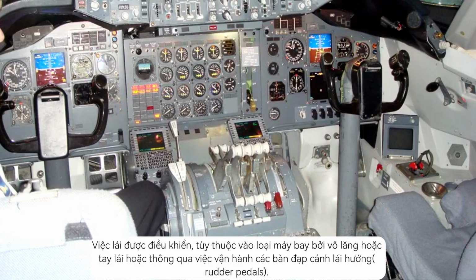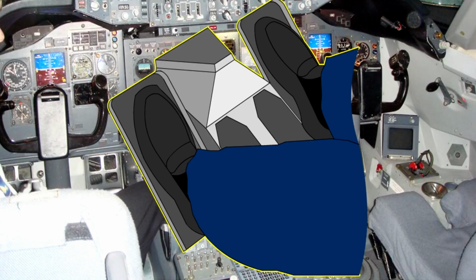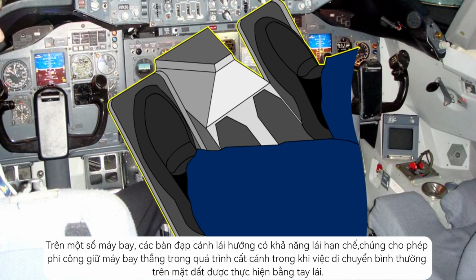Steering is controlled, depending on the type of aircraft, by either the steering wheel or tiller, or by the operation of the rudder pedals. On some aircraft, the rudder pedals have a limited steering capability, allowing the pilot to keep the aircraft straight during takeoff, whilst normal ground maneuvering is achieved using the steering tiller.